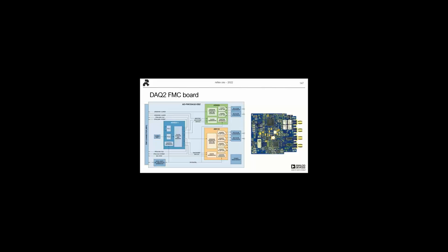We have the 4 transceivers for it. You have all the system clocks, the whole clocking chain that will be used to set up the clocking of the FMC, the clocking for the analog converters. And that's really easy to use with the Analog Devices framework. I will go into more detail on the next slide.